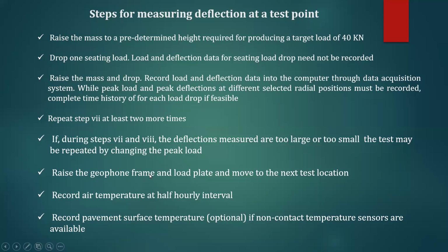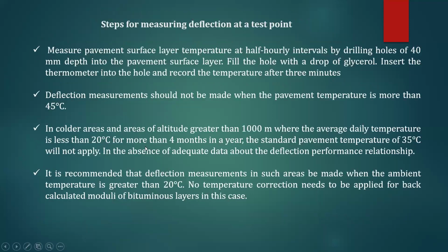Temperature also needs to be measured at regular intervals. Time intervals are most important. So measure the pavement surface temperature at half-an-hour intervals, by drilling 40 mm, as I told already. You have to fill that with glycerol, and using a thermometer you can measure the temperature.